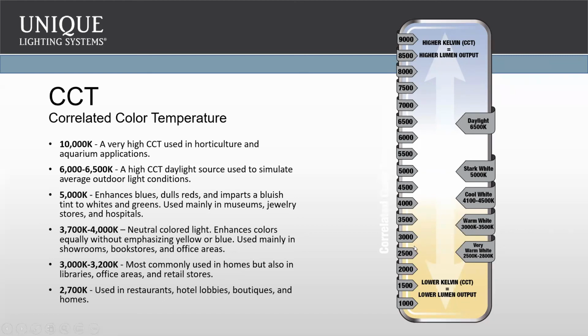I have a couple of theories why I think people are going that direction. I'll tell you one theory is that I think people go 2700 is because we were all conditioned that was the color of landscape lighting. Back in the halogen days, those bulbs only lasted 4,000 hours. And so to extend the life of them, people were putting less volts to them, putting them closer to 10, 11 volts to try and extend the life out of them. And when you put less volts to a halogen lamp, you get that real warm, 2500 look. And so we got used to that. Now with LEDs, they're running 40,000, 50,000 hours. We don't need to have that look as we go through.